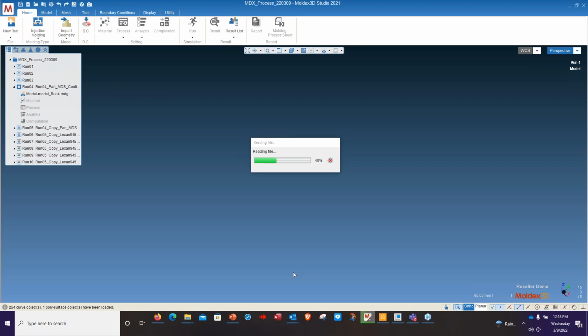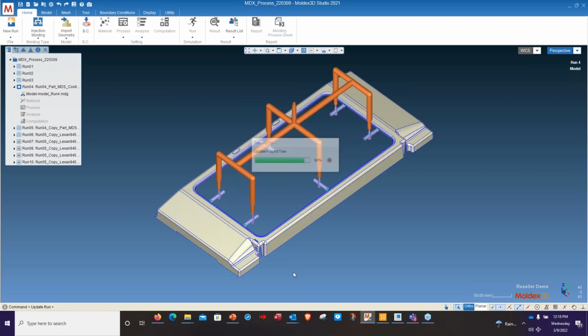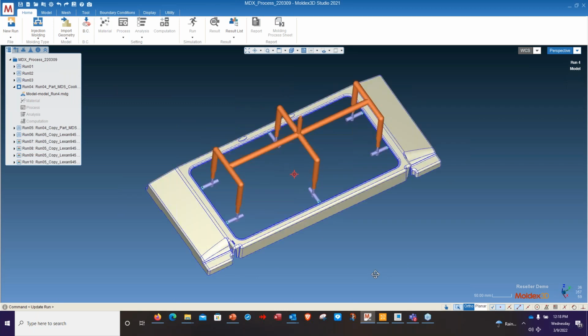So again, going through the process, typically once you mesh that, and if you have to fix anything, you probably could have restarted. Moldex 3D has some built-in tools to adjust the meshing. Sometimes the mesh size might have been a little too big. So by refining, making it a tighter mesh, which is going to add more elements, you can go through the meshing process. That will take care of some of the issues, especially if it's small edges.